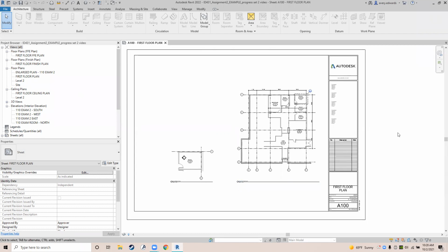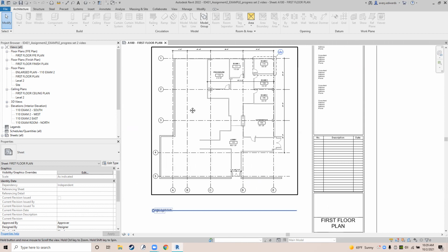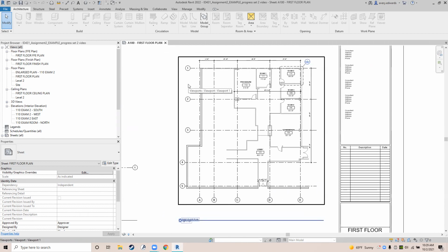When you are doing a renovation or addition project, a project where you're working with part of an existing building, so everything is not new construction from the ground up, you'll have existing building components, walls, doors, floors, ceilings. But then there will also be new construction. So, of course, you may be adding new walls or floors or doors or ceilings, or you may be demolishing some of those same components. So in Revit, you set a phase to say which phase of the project building components are. So they're either existing or new construction.